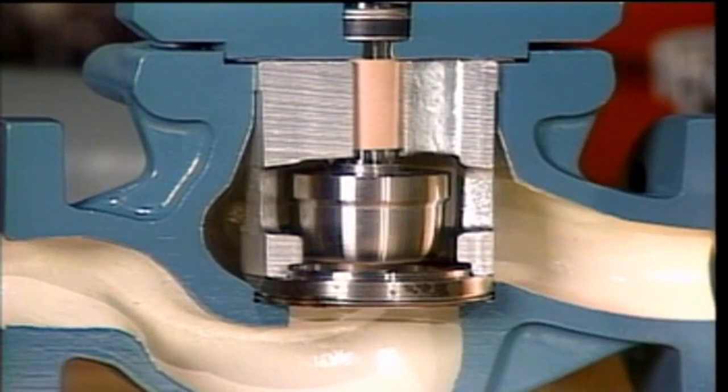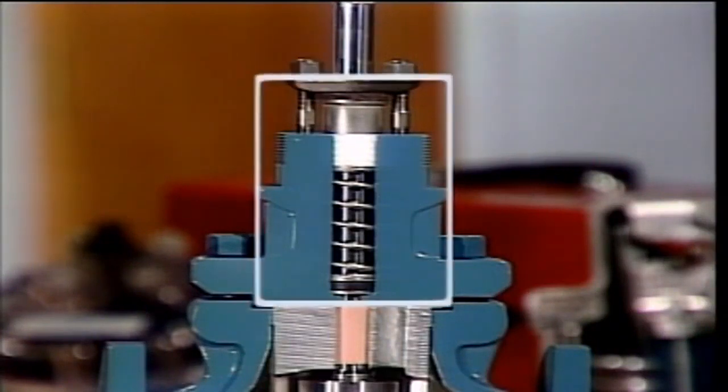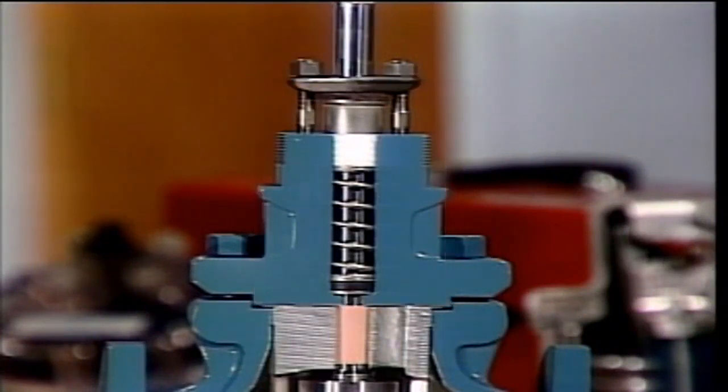It has the same basic parts as a manually operated valve, including a valve body, a disc, a seat, a bonnet, a stem, and a packing assembly. Control valves also have parts that may not be on manually operated valves. For example, control valves, like this one, generally include guides that align the valve stem and disc with the valve seat. These guides help ensure precise control when the valve is opened and closed.